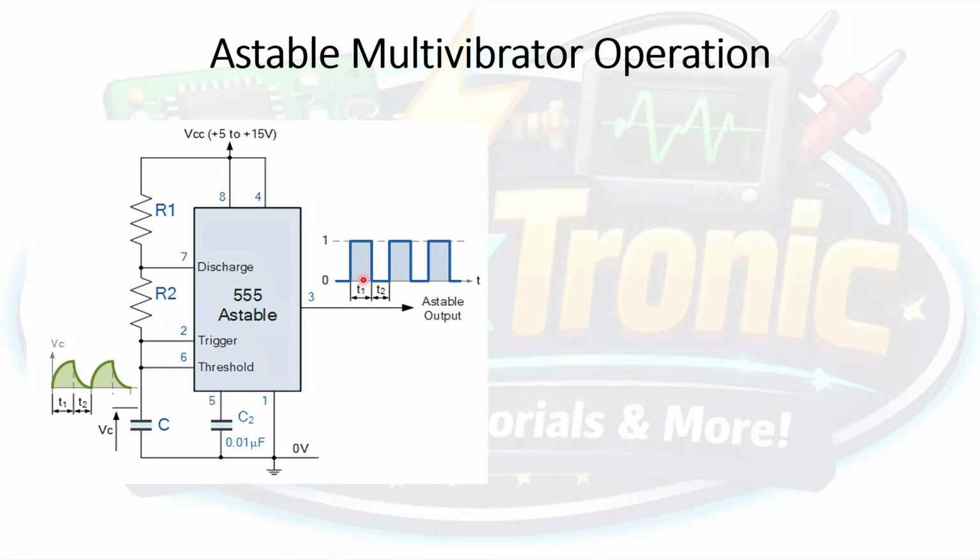Our second channel is connected here at the capacitor side of the circuit, actually between R2 and the capacitor. Now, what do we expect to see at the Y2 channel of our oscilloscope? We will expect to see something like this. As I mentioned in the previous video, what you will see on the Y2 channel is the capacitor voltage.